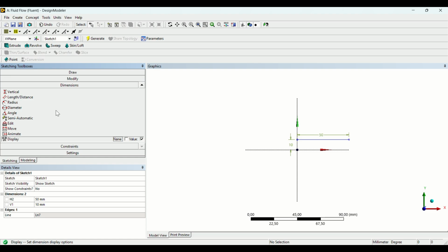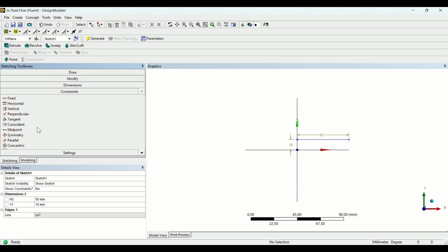So you can also put some constraints, as I was mentioning before. For example, imagine that you create a line and the age didn't appear because you were in a hurry. So you can, for example, use a horizontal constraint. So we'll make the line horizontal. And you have here some of the most important ones in case you want to have some symmetry or something like that, you can use the equal length, equal distance, and also the symmetry option.